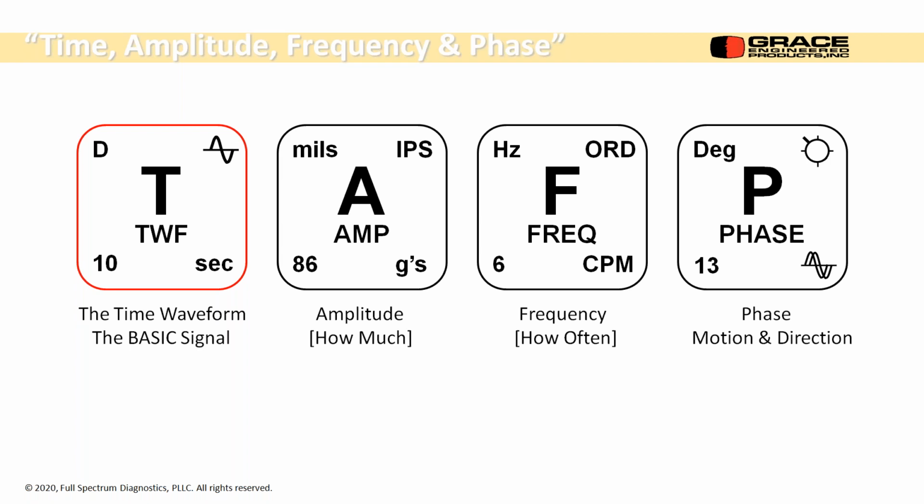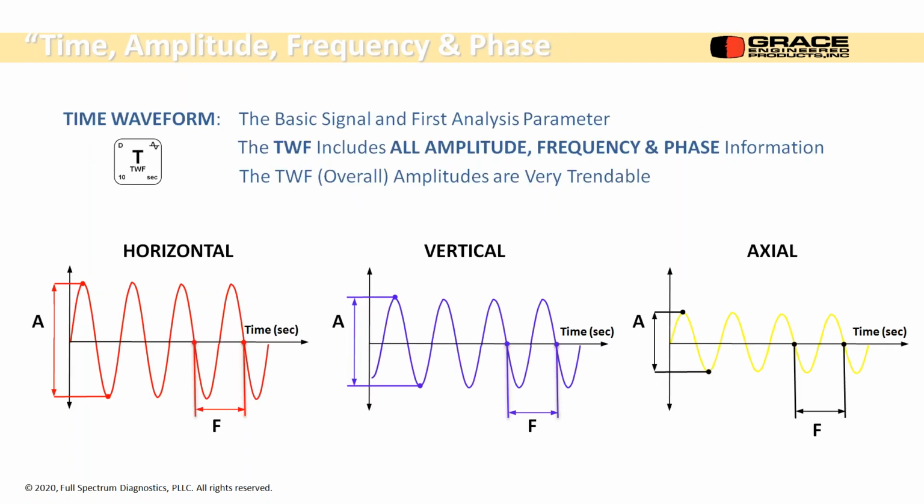What makes it incredibly useful is there's about 12 different problems that all have the same frequency signature. They show an elevated 1 times RPM response. So basically everything, if you're looking at the table, everything that's a synchronous problem in the first 2 columns of the table plus natural frequencies, that can be what we're looking for. We're trying to distinguish all of those things. And phase analysis allows us to do that. We'll show you how that happens.